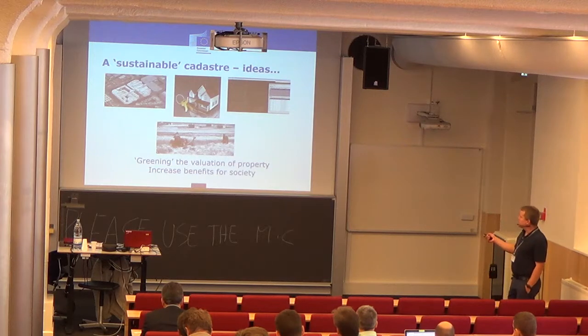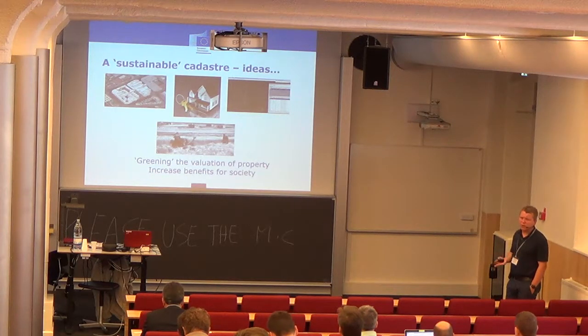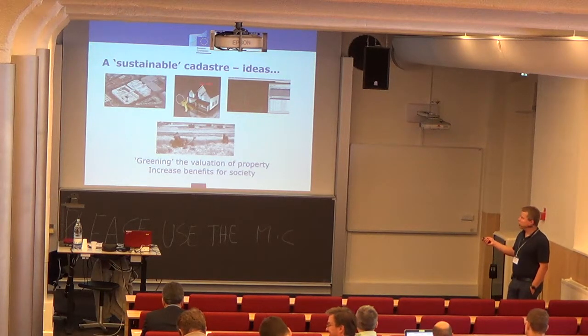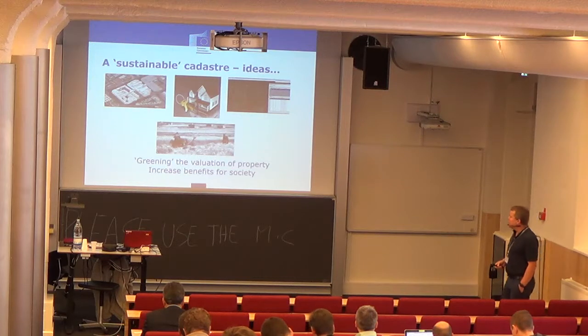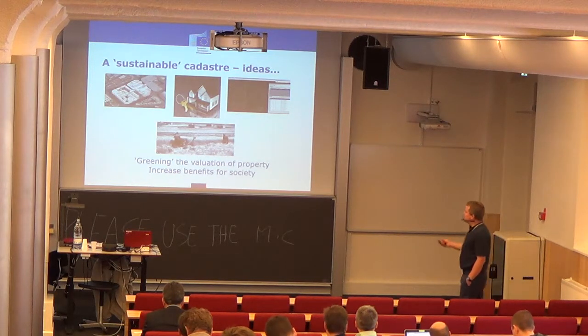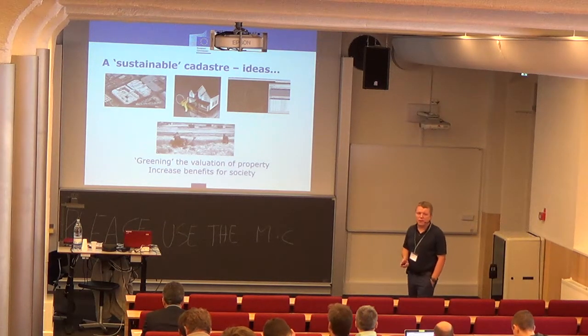But I would say cadastre is something which is also very important, and traditional cadastres usually use only 2D data, so in 2 dimensions, but today there are a lot of requests for 3D data, and some countries have already started to develop these 3D cadastres, like the Netherlands and so on. And it seems that this is really the future trend in the cadastral system.